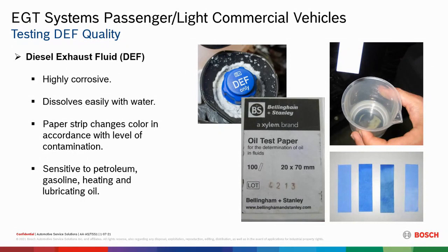And similar to DEF fluid in the diesel fuel, the opposite does happen where people put diesel fuel in a DEF fluid. I don't think it's quite as costly when you do that, but they can do that. So there are test strips for this that aren't cheap, but you can stick these test strips in. They'll be white when you begin. You stick them in there, and the different color of blues or the intenseness of the blue will determine how much and the type of fluid that's in the fluid itself. So these are available as well to everybody out there to test for the contamination of the DEF. And believe it or not, it does happen. It's crazy how could gasoline get in there, but honest to God, it happens.